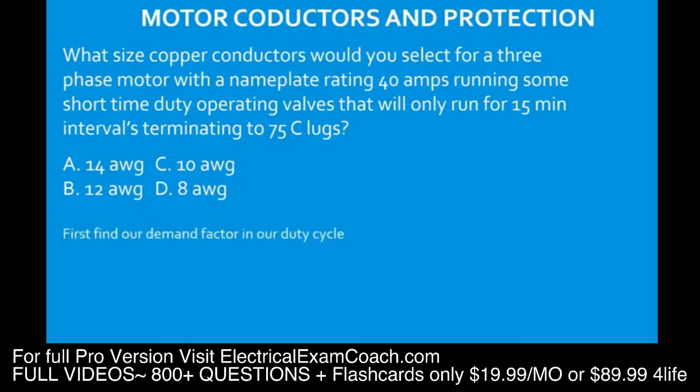So we see that there's something going on here, and we recognize that it's a duty cycle question. We're going to head to our demand factor table for duty cycles. It's 430.22(E). Then starting on the left-hand side, we're going to look for our situation. In this case, it's short time duty operating valves. When we find it, we come over and tee off with our time, which is 15 minutes, and we're going to find a demand factor of 120%.